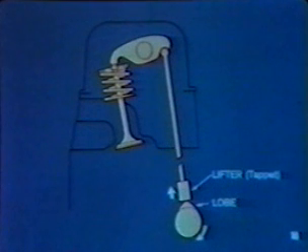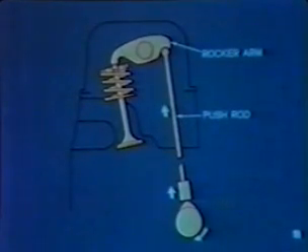As the camshaft turns, the cam moves against the valve lifter, which also may be called a tappet or cam follower. The lifter is raised whenever the lobe of the cam is up and allowed to come back down as the lobe moves past it. Above the lifter is a push rod, which moves up and down with the lifter and transmits the cam action to the rocker arm.